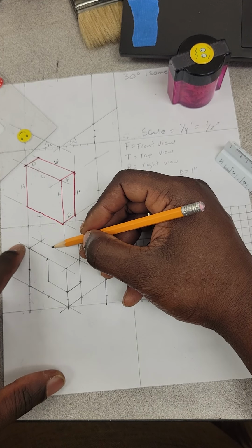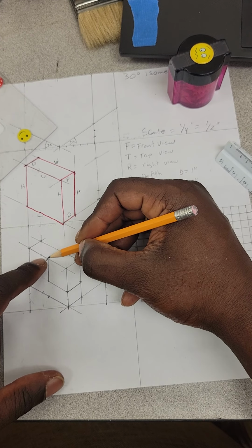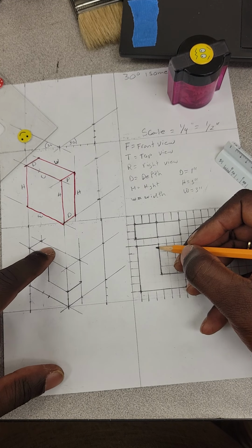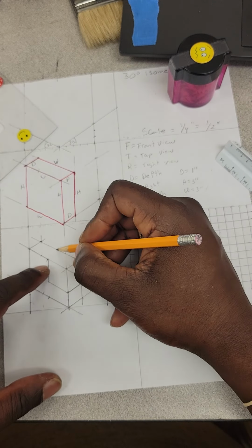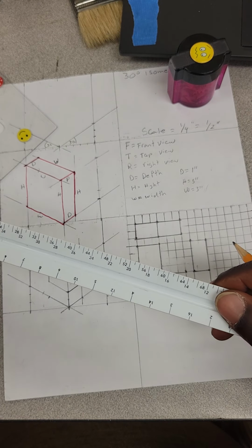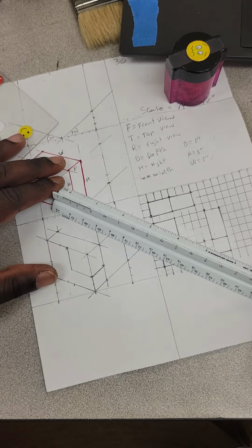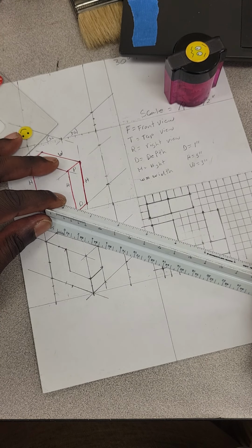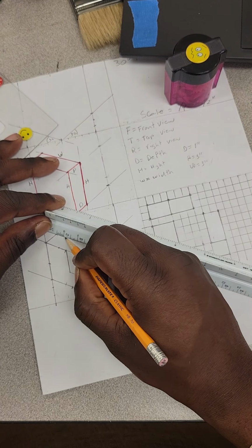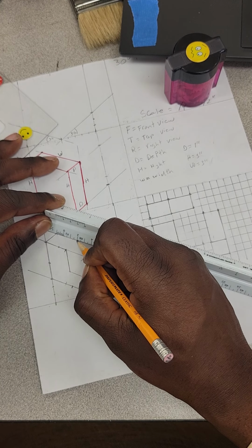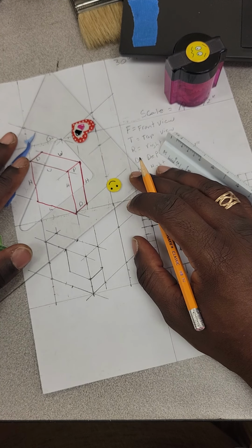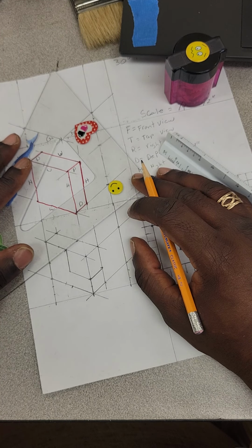Well, we're already on a 30-degree angle. We can actually measure down to this point, measure down to this point, and we can get this point here by knowing this point right here, which is 1.5 inches. We can measure down 1.5 inches. We connect these 2 lines, and we have our mark just by going off what we know already. There you go. That's the top of your box on a 30-degree angle.